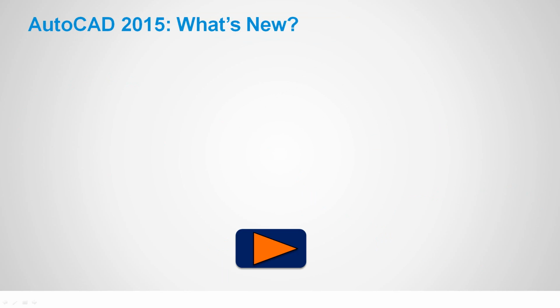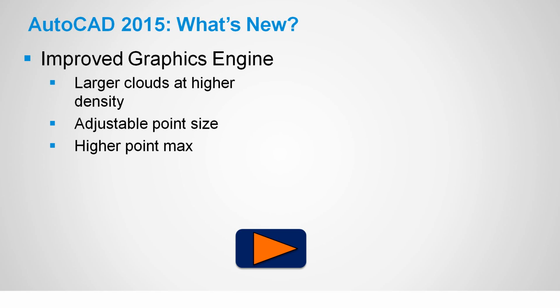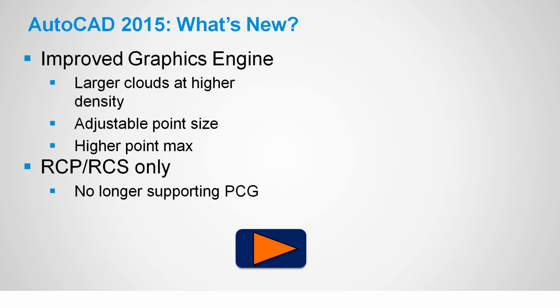So AutoCAD 2015, what's new? Well, what you'll notice right away is an improved graphics engine, and this is a great improvement. This means larger clouds at higher densities. You can adjust the point size and you can create a higher point max, and I'll show this in a video. In addition, you'll find that only the RCP and RCS files are supported. The PCG file is no longer supported in AutoCAD 2015.